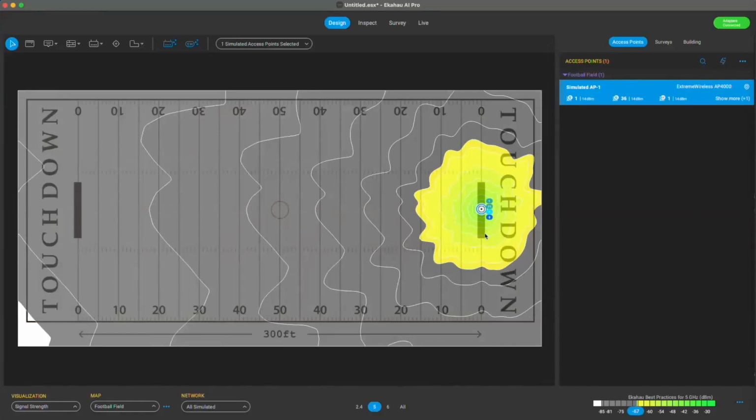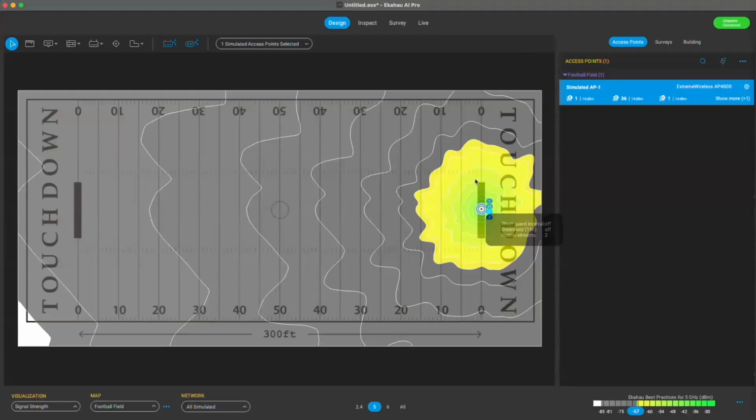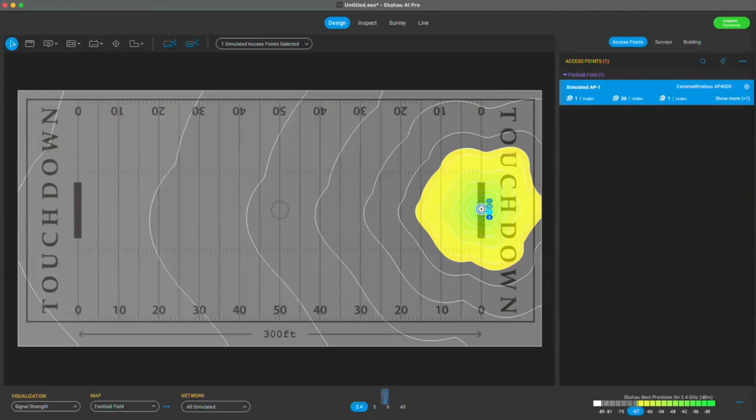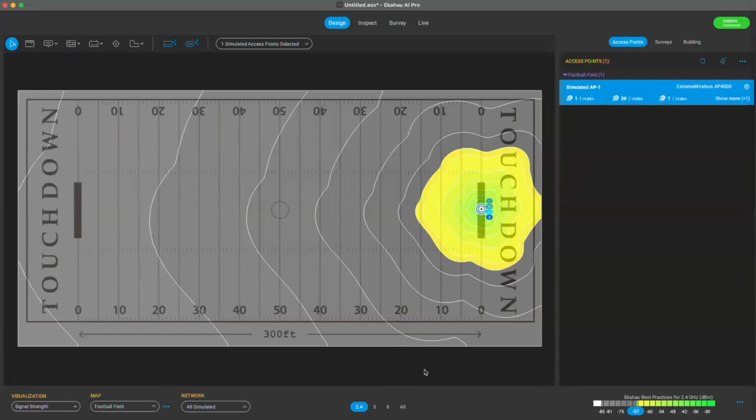It might be due to the fact that they are using different sets of antennas, they have different radio chains, and they might have different antenna gains. So let's check that out. Actually, EIRP takes into consideration the transmitting power levels. They are all the same across all three bands, and the passive antenna gain is also very similar. So the coverage pattern from the antennas on the 2.4 gigahertz band versus the 5 gigahertz band seems to be different in a way where 2.4 doesn't cover way more than 5 gigahertz. But let's focus on 5 versus 6.